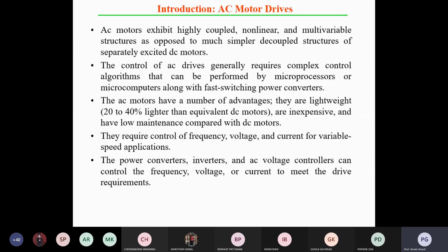At the end of the day, for the very beginning you should fetch the analog input. What are the analog inputs? Normally we are fetching the motor speed, in the outer loop. In the inner loop other kinds of parameters you can also collect, but normally we are taking the motor speed. We have to maintain a fixed motor speed. So the motor speed all the time should be measured through tachometers or other kinds of sensors, and after using the transducer you will get an electrical signal.